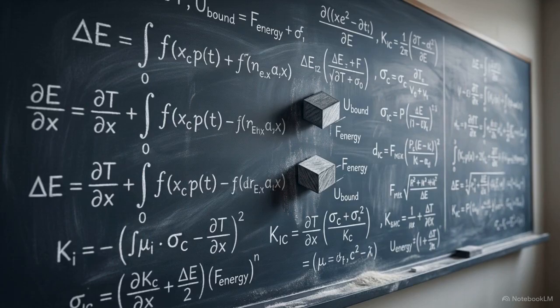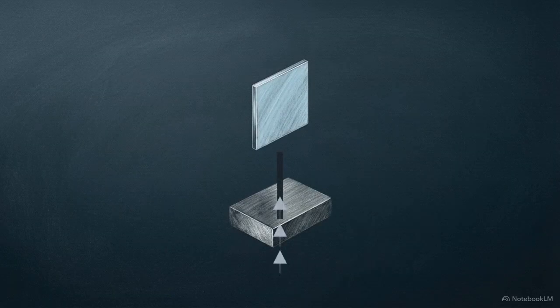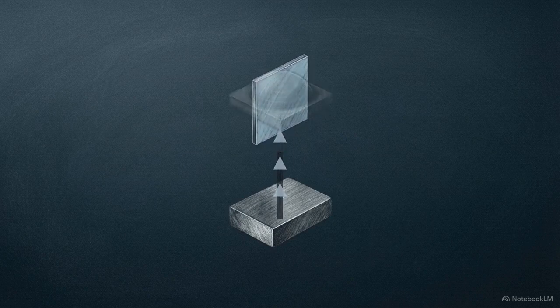The most sophisticated tests move away from measuring raw mechanical failure loads toward advanced fracture mechanics, the calculation of required energy. The primary tool for this is the blister test, which initiates a controlled active debonding process. Pressurized fluid or gas is injected into the interface through a microscopic hole in the substrate. This forces the coating to bow upward, forming a symmetrical dome or blister.